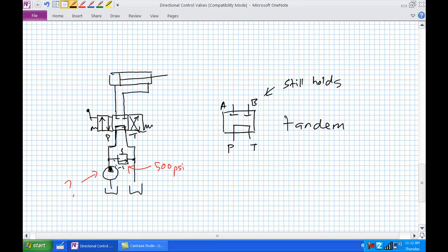But at what pressure is the pump operating now? Well, in a closed position, it had to achieve 500 psi for that relief valve to open. Well, what's your pressure at the reservoir? Ideally, incredibly low. So basically the pump is going at reduced pressure, whatever pressure the reservoir is, let's say 20 psi or whatever it is, extremely low. The pump is operating at a very low pressure, i.e. it's operating more efficiently. It's not using as much energy, okay?